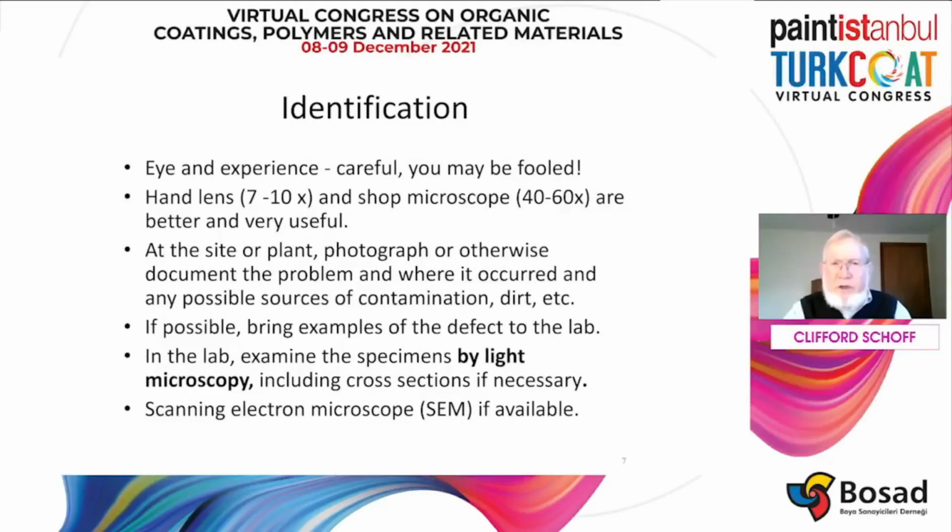Identification, the first thing usually is just looking. And if you're very experienced, you may well be able to determine what the defect or the problem is. But be careful, you may be fooled. I've been fooled more than once, I can tell you that. I often use the hand lens or a shop microscope.